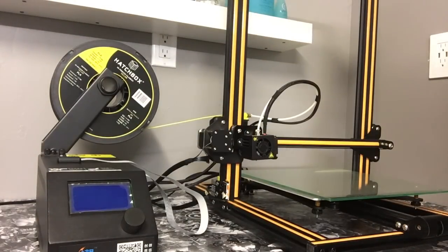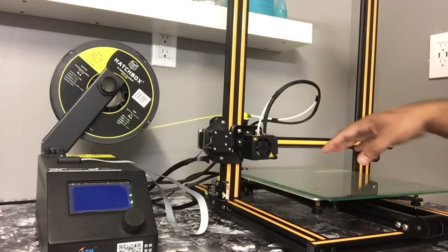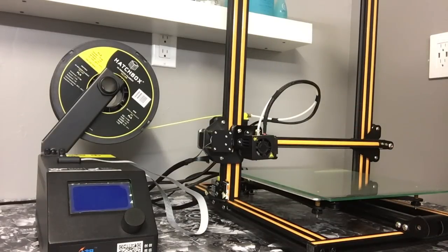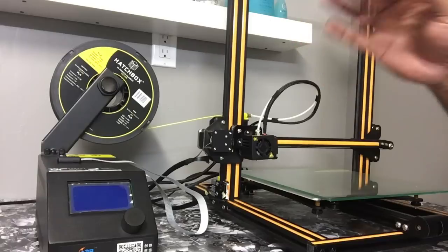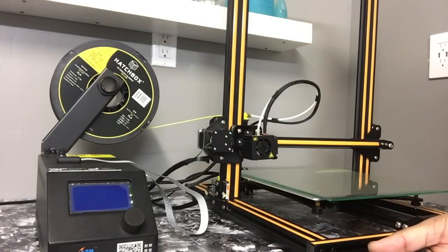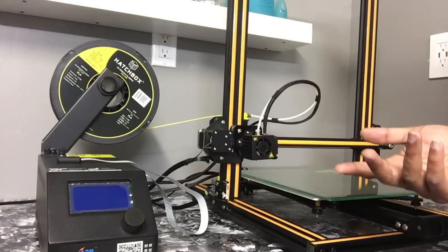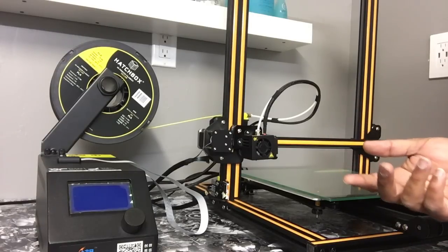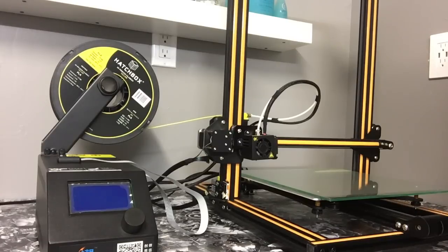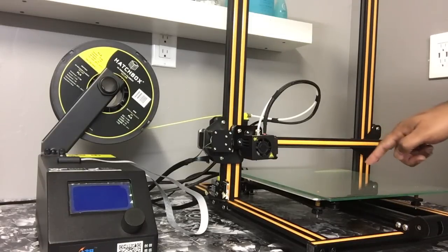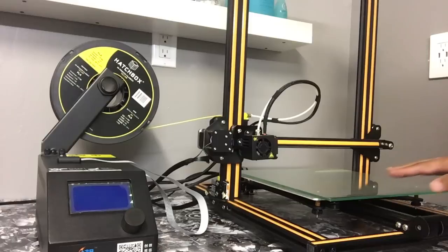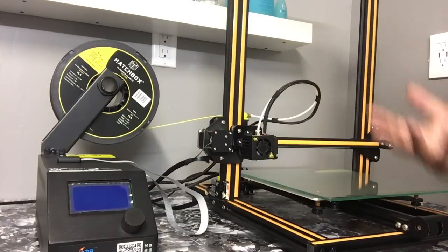So the reason your bed isn't leveling, one of the main reasons I found out, is your center's warped. If you flip it, maybe there's a bubble on it. But one thing you can do, if you're not 100% sure, is download files from Thingiverse or MyMiniFactory, a bed leveling calibration file. Basically it'll just have a square here, here, here, here, and one in the middle. So that's the 5 points it's going to check, and it prints out a very thin layer, and you can see if it goes up or down once you take it off.